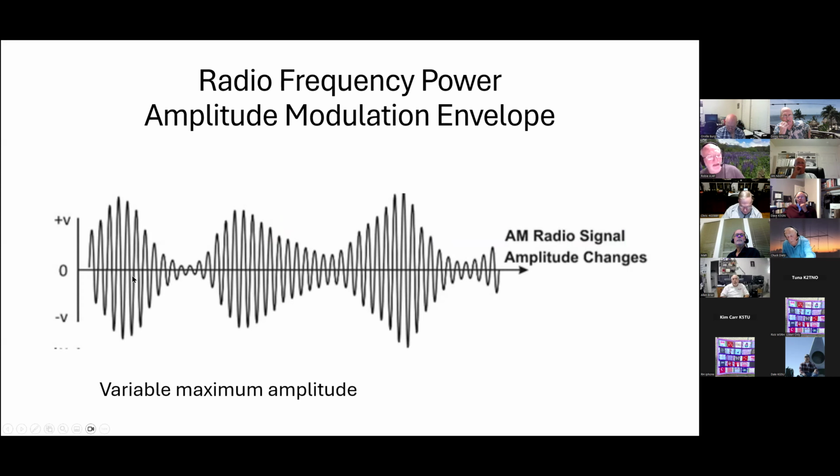So a trick would be to rectify this voltage and put a capacitor in there and let the capacitor charge up as this voltage went up. And that's pretty good up to a certain frequency, but then it seems to not work at really high frequencies. And then you can put an amplifier behind that with a hold circuit that will actually detect when the voltage stops increasing and hold that value, whatever it is. And there's ways to do that electronically. So there's several methods that all should be pretty good.